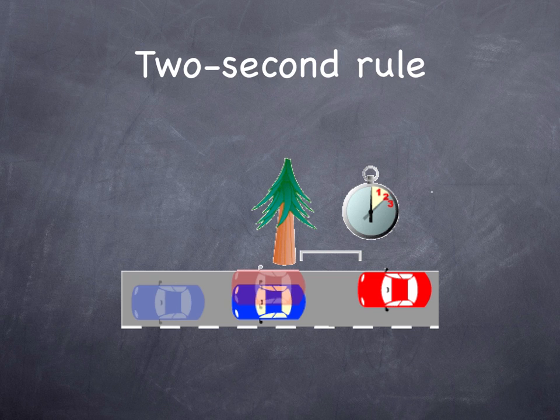In practice, some locations see as many as 2,300 vehicles per hour, with some consistency. So cars in congested situations, not necessarily slow heavy traffic, but still driving at or near the speed limit, can get 2,300 cars per hour past a point, which means they're following at less than 2 seconds. If they're following at 1.5 seconds, it is 2,400 vehicles per hour past a point.